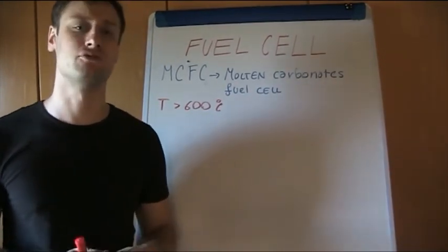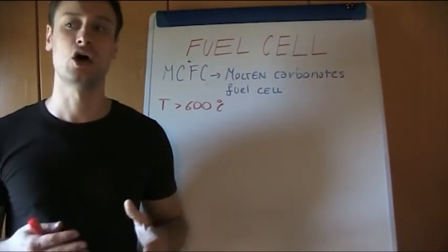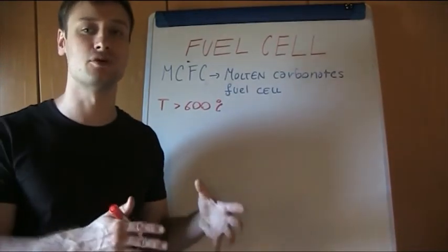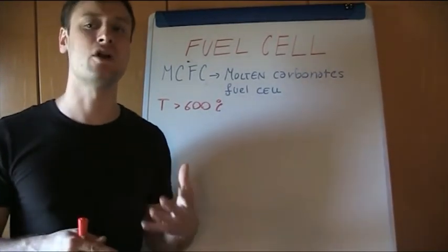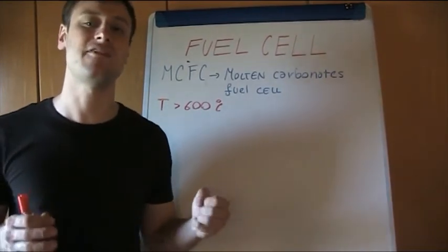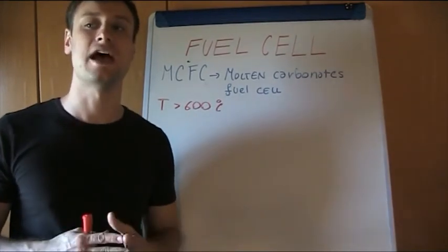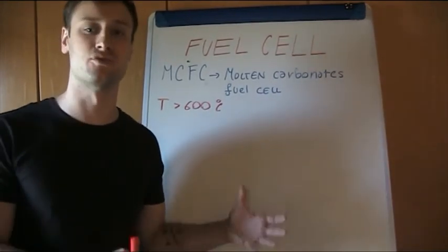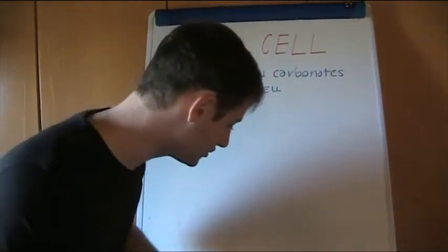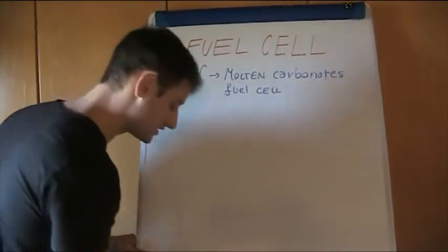And this is also the reason for which, in general, the long-term stability of this cell is not as good as in the case of the solid oxide fuel cell. This is one of the only advantages that is not shared, because in this case the lifetime is significantly reduced with respect to the solid oxide fuel cell due to the highly corrosive environment created by this type of electrolyte.